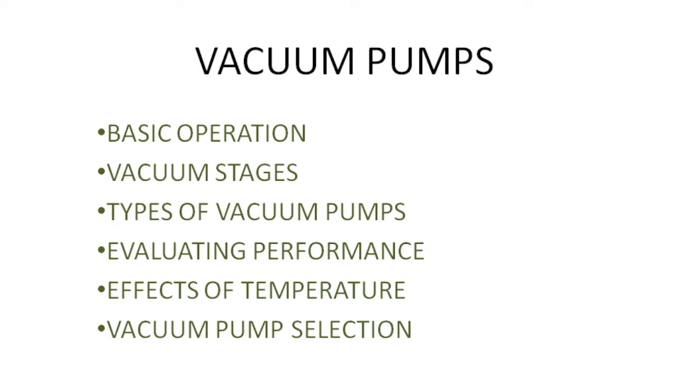Then there are various other types like reciprocating piston pumps, diaphragm pumps, rocking piston pumps, and rotary vane pumps. The rotary vane pumps are important because most rotary vane pumps have lower vacuum ratings than can be obtained with a piston design. The rotary vane design offers significant advantages like compactness, large flow capacities for a given size, lower cost, lower starting and running torques, etc.